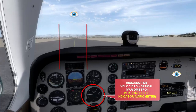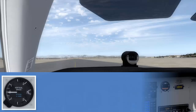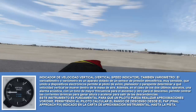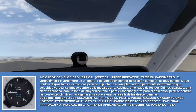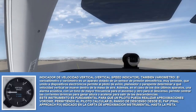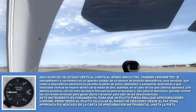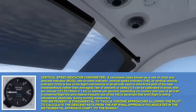That is the variometer, or the vertical speed indicator, and the vertical speed indicator is absolutely vital to tackle a VOR DME approach. And why? Because you can program, or you can follow descent rates. Okay, and when flying the aircraft it is very important, because sometimes you will need to ascend at a certain vertical speed, and sometimes you will need to descend at a certain vertical speed. That will be the vertical component of the aircraft, and when the aircraft moves to the left or to the right, that will be the horizontal component.